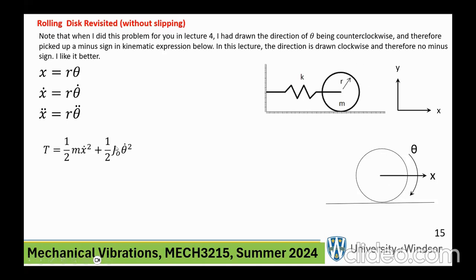So we know from mechanics and dynamics, 1/2 of, because it's a rotational motion, it is not m, it is the polar mass moment of inertia about the point O being the center, for example, CG, and then theta dot squared. 1/2 J omega squared, omega is theta dot.